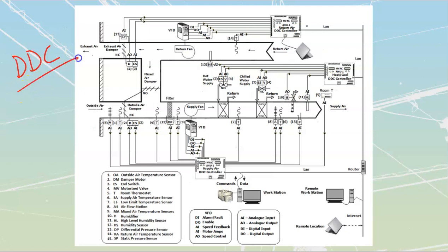What a DDC system is, is a pre-programmed PLC that, instead of you having to assign pins and all that other stuff, just has check boxes. This pin's already assigned to it. You're going to attach to specific terminals on each of my DDC controllers. Those individual DDC controllers, all we do in the software is state what this is connected to, etc. So it's mostly pre-programmed. We just tell the DDC system that this input is a temperature sensor, and it is in this room. And then the DDC categorizes it and makes everything control off of that.